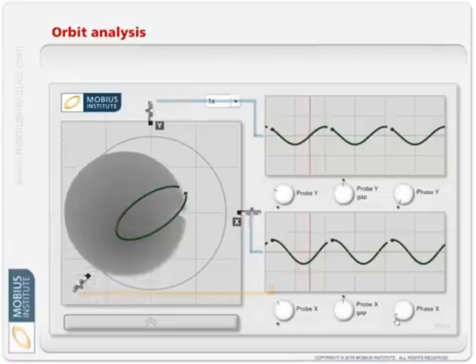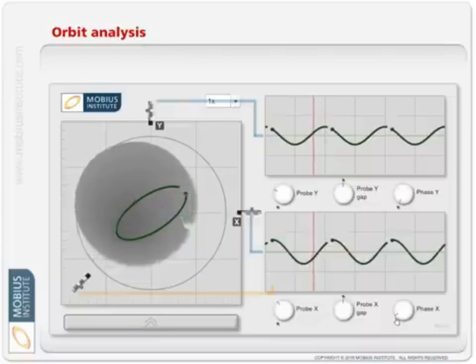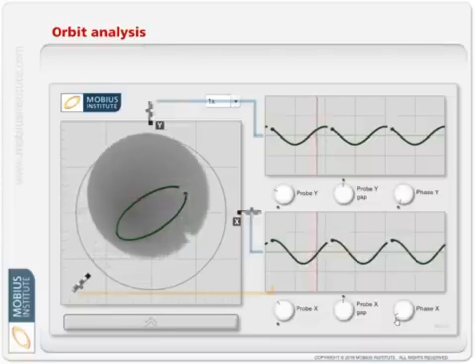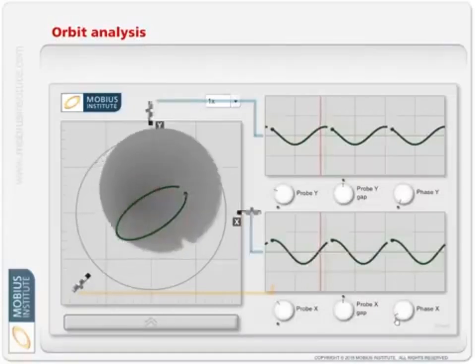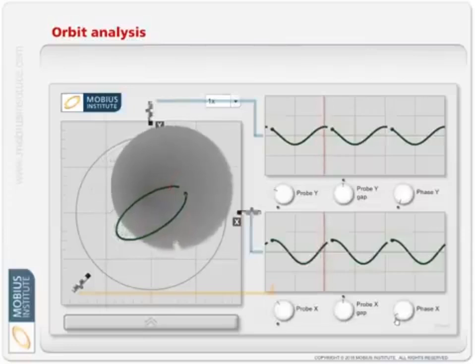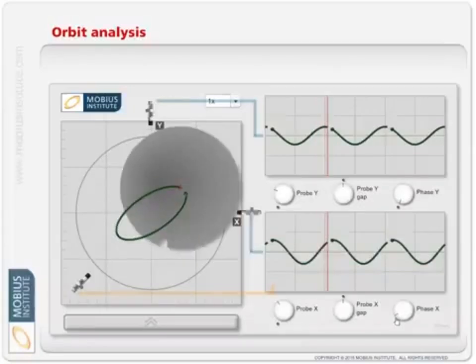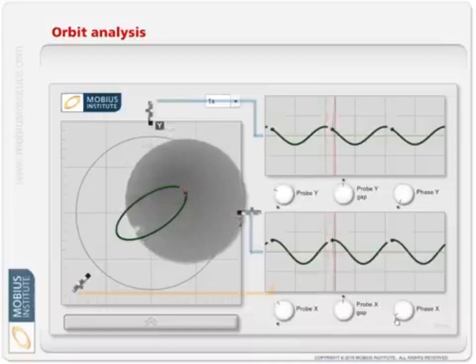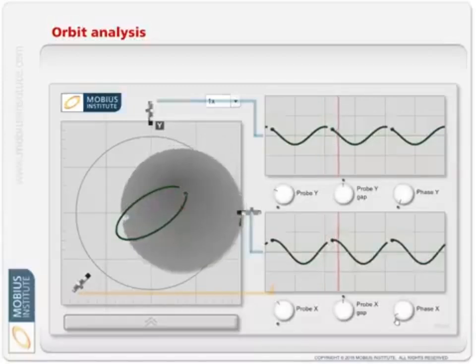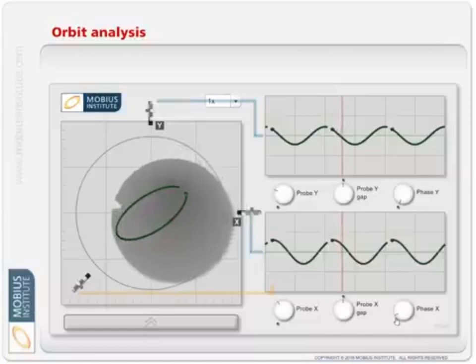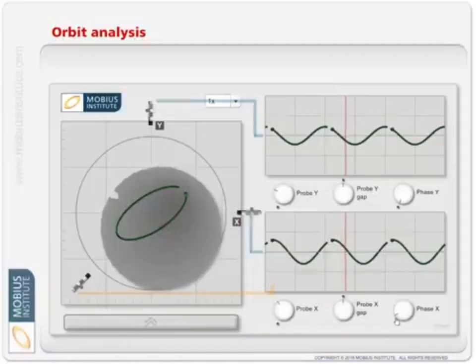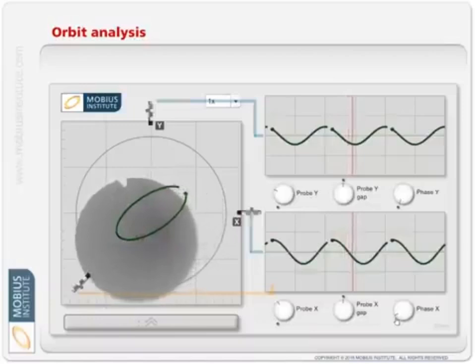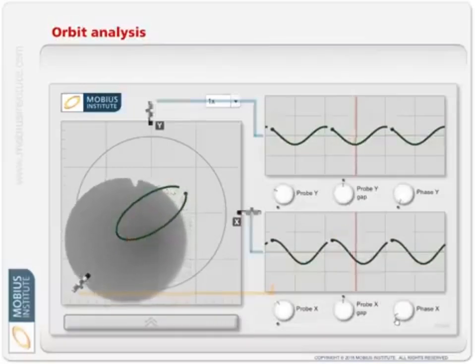It doesn't necessarily stop the machine from developing the fault in the first place. That's for a different discussion about reliability improvement. But vibration analysis gives us an insight, and now we can decide if there's something we can change about the way the machine's being operated, if there's something simple we can do to alleviate the problem, to extend the life of the machine, or we can start planning the maintenance.